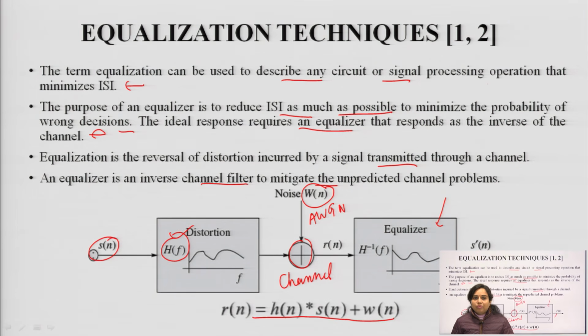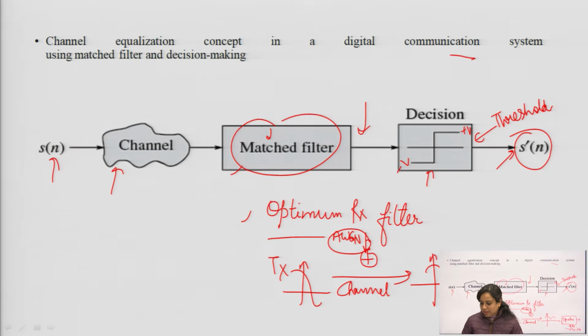Then we have seen the different types of equalization techniques, where we have to minimize the intersymbol interference problem. What is the intersymbol interference problem? When more than one transmitter is transmitting a single signal, the waveform will disperse. Due to this dispersion, it may be possible that the first version of the signal and the second version of the signal collide together. That means they overlap together, which will cause the loss of information. So, that is the main drawback that the equalization technique addresses.